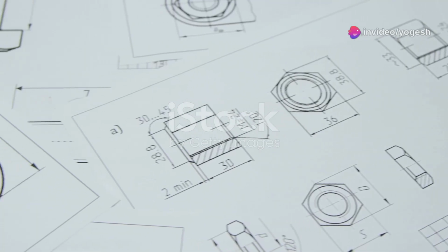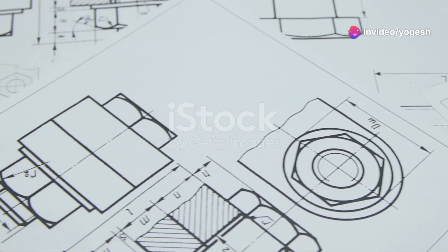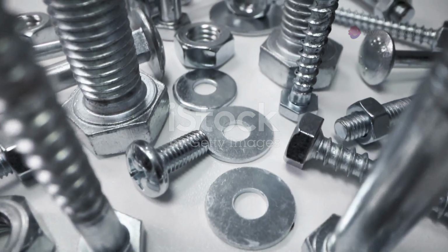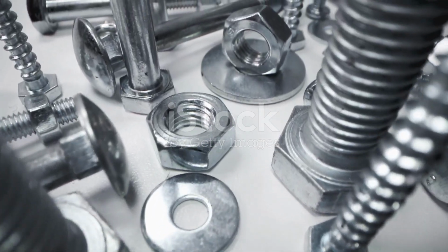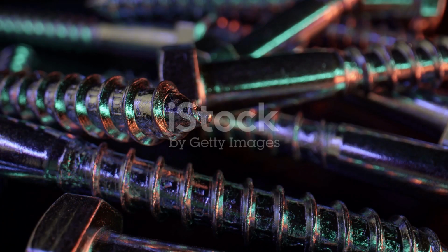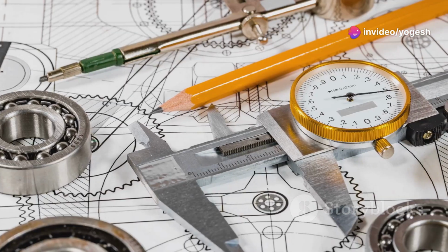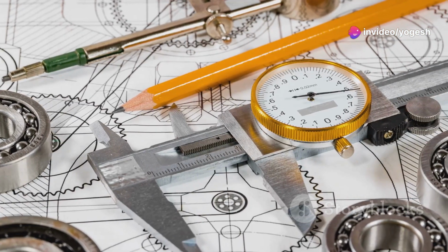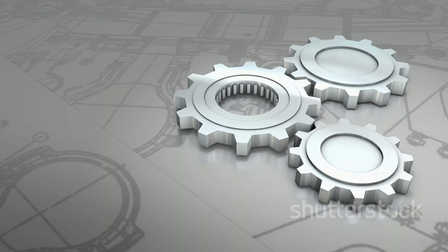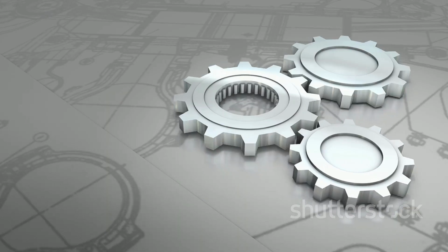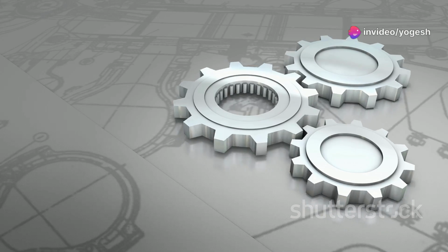Section 7. Fasteners at a glance. Standard symbols and shapes for bolts, nuts and more. While meticulously drawing each individual thread is important for detailed representations, there are standardized symbols for common fasteners like bolts, nuts, washers and screws. These symbols simplify the drawing process and make it easier to interpret technical drawings at a glance. For example, a bolt is typically represented by a rectangle with a thick line representing the shank and a thinner line representing the thread.